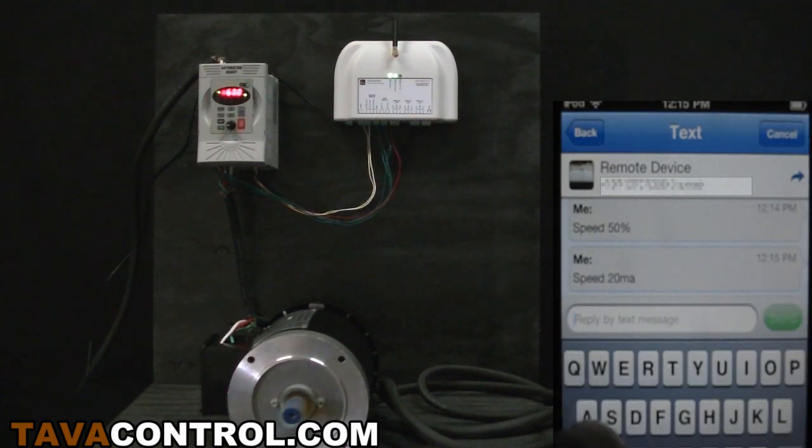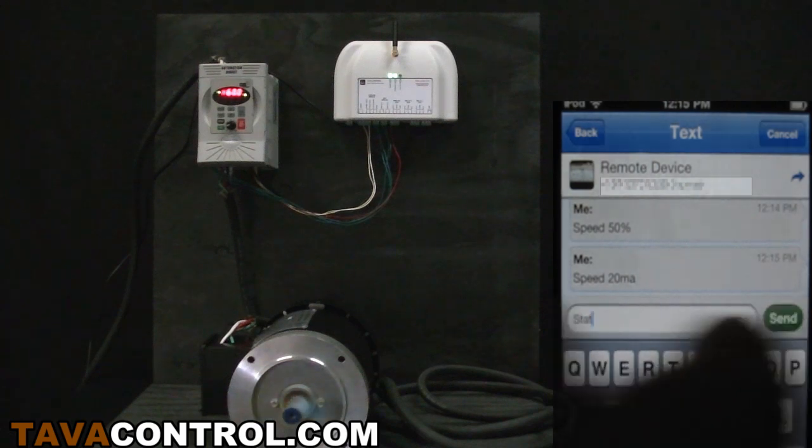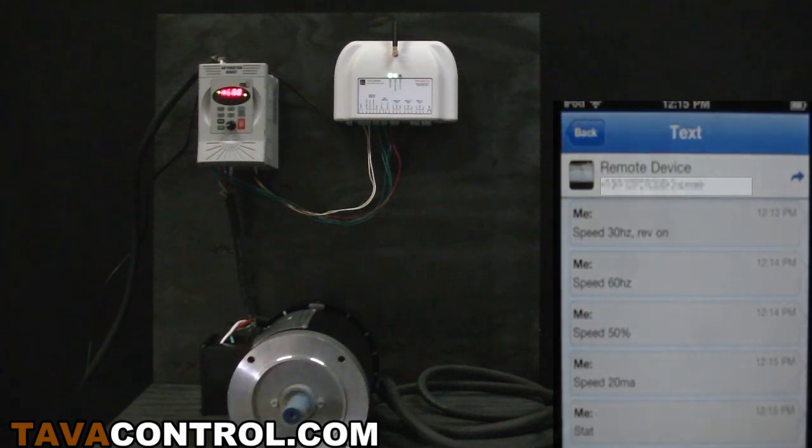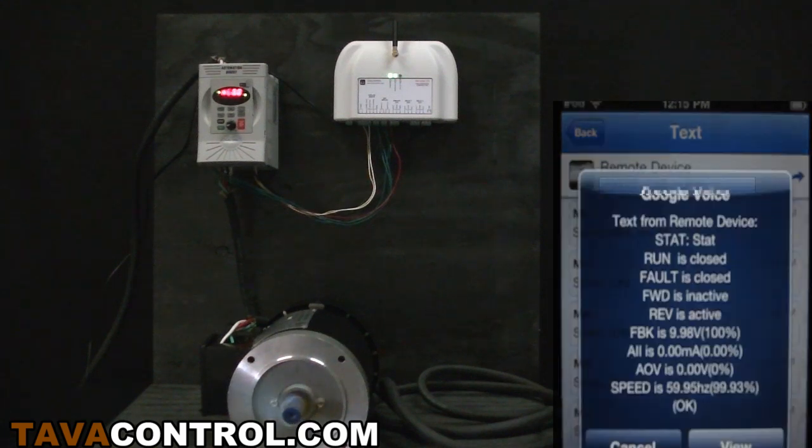I showed you changing the unit on one of the analog outputs. This could also be done on the analog inputs. For example, if you were using a pressure transducer on one of the analog input terminals with a range of -10 to 10 inches of water column, after setting up the unit, minimum and maximum values for that input, your status report will have the input value converted to the appropriate unit.